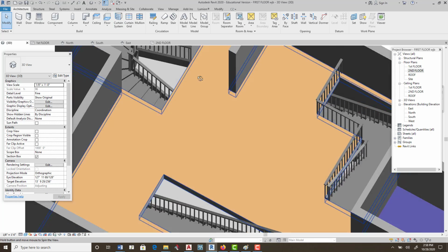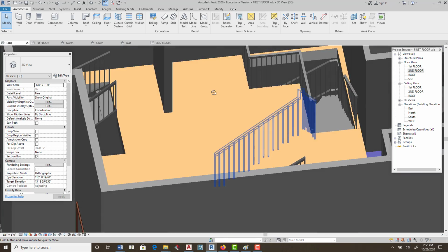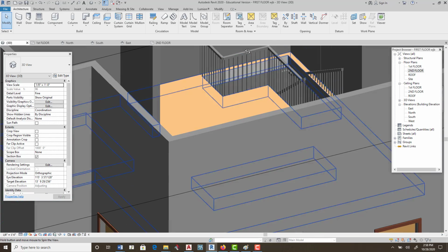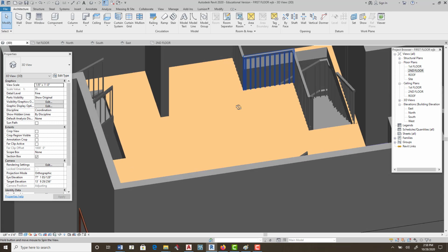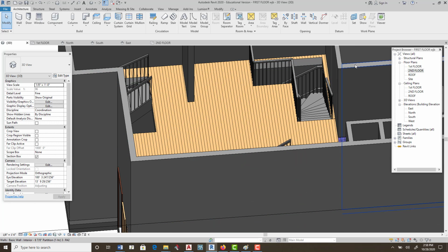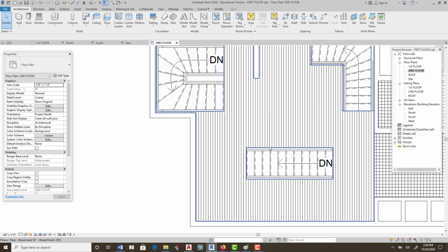Alright, so let's go to the railing. Wow, so now know that the children will fall over. See, it's kind of institutional. There's other railings that way. Remember you drew your railing can't be more than 4 inches, otherwise a child, if they can slip their head through there, which is more than 4 inches, they can fall. So anyway, that's very generic.